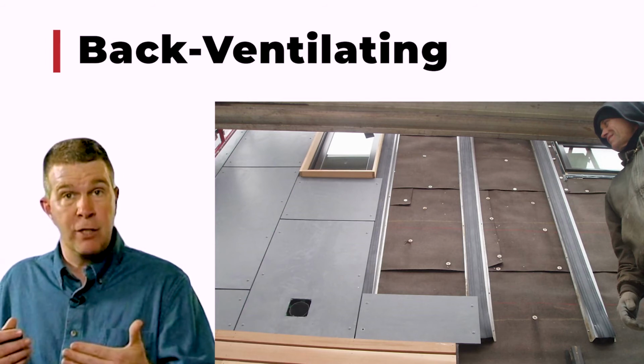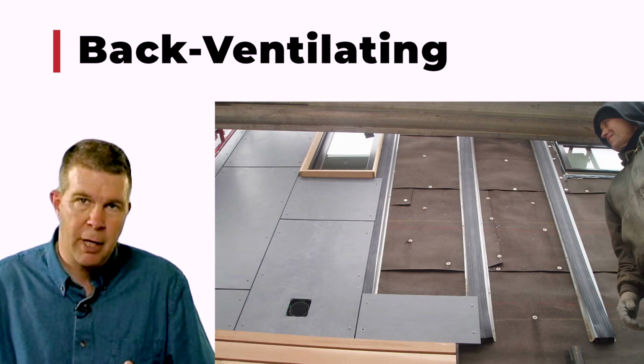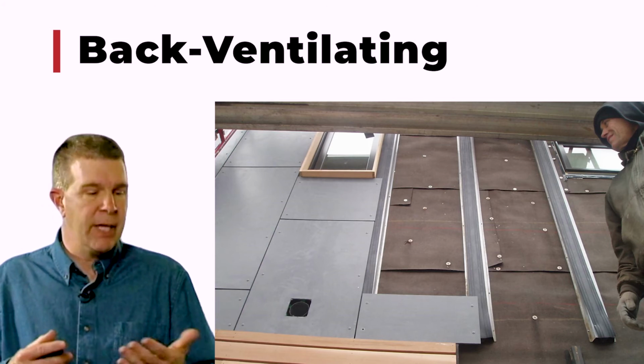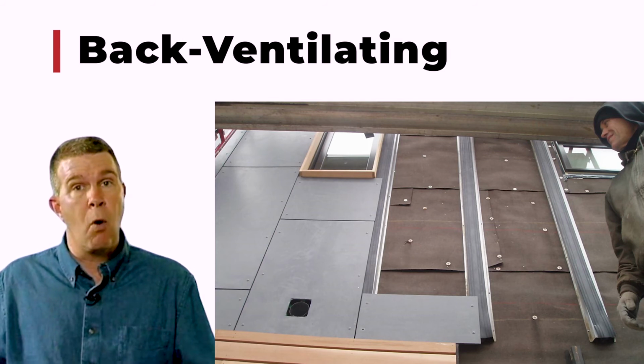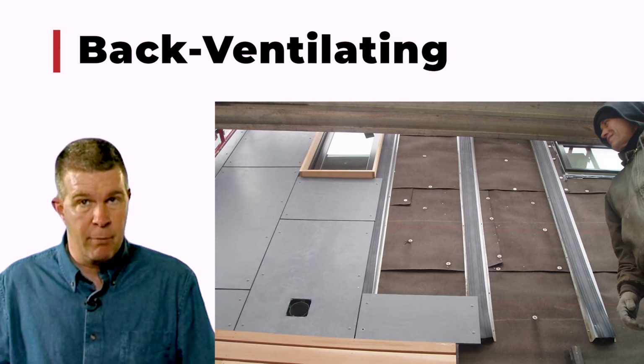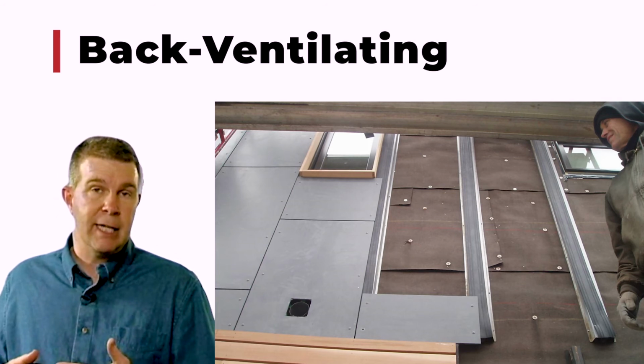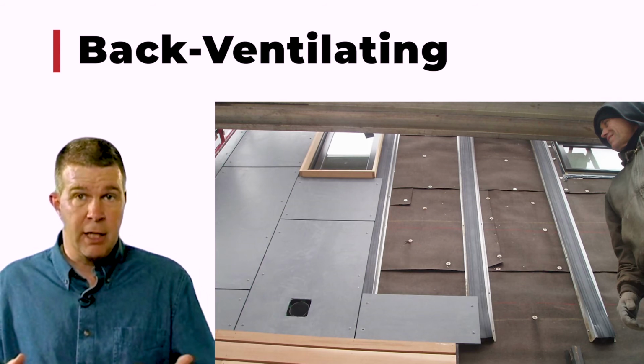And in between that as well, we need a drainage plane. What's a drainage plane? It is either going to be the felt or the house wrap that directs the water down and away from the SIP when the siding leaks. And you know that sidings leak always.